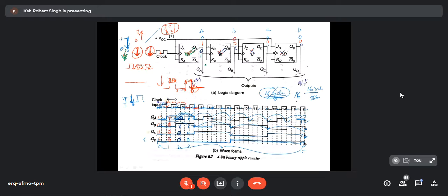0 to 1. Earlier it was 0, now 1. 0 to 1 is not negative going. It is positive going, it is up. That means it is a positive edge trigger. If it is a positive edge trigger, then will this B be alive or dead? B will not work. So what will be the output of B? No change, 1. Correct, good.